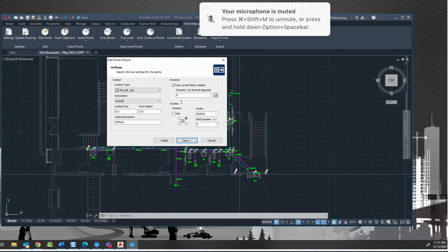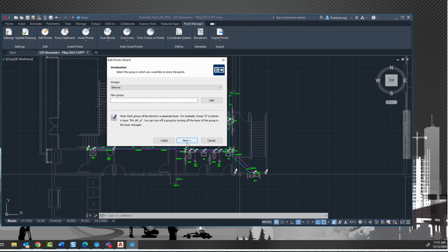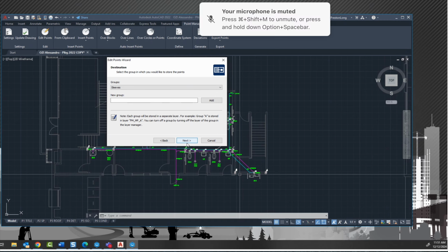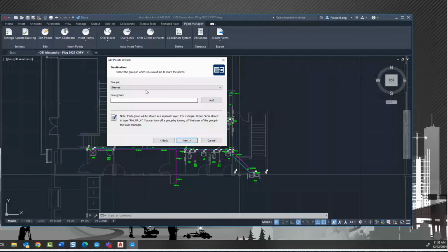Okay. I see. And then it would update them all. If that makes sense. Yeah. Okay. So it's not like it's broken. If you did your blocks like that, you can fix it by just inserting them in the block. And the cool thing about the insert inside the block is if you got like an inertia base or anything like that where it's got 4 points that you want to mark out in one object, you can place all of those marks in there, and then every time you place that block, all 4 of those points are going to show up every time.